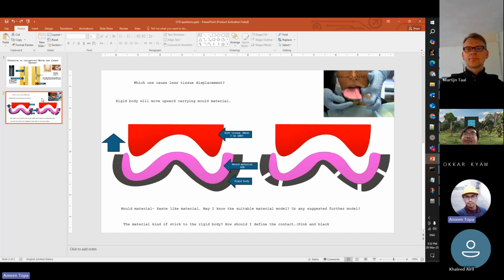And yes, you can use SPH. If you want to go with a 2D, then you do not need to use SPH. You can just use 2D with adaptive refinement. That will be a better option in my understanding, because it will be much cheaper.